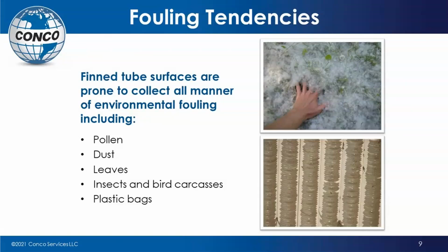The picture on the top right shows the pollen. Now, anybody that lives in the Northeast like I do knows that every spring we get a lot of this stuff. It's on our cars. As that is floating around in the air, it's also being sucked up and pushed up into these fins, and it is sticking between the fins, thus limiting the amount of airflow that goes through.